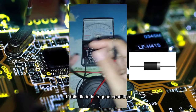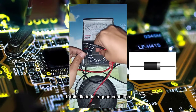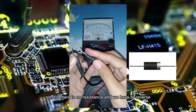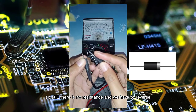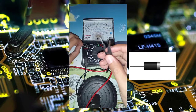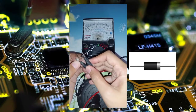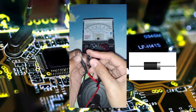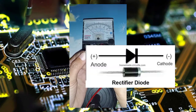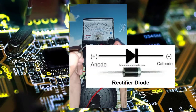Then just to check, put it in 10K to see if this diode is in good condition. So still there is no resistance, and we have to reverse. So there is no resistance, so this one is a good diode.